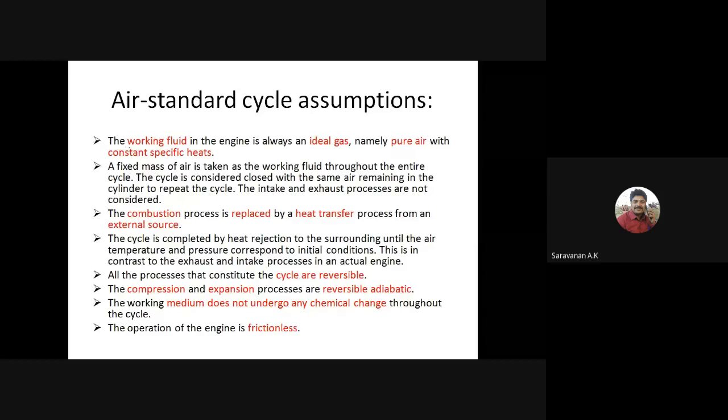So the first term is the working fluid. The working fluid is pure air with constant specific heats. Pure air means an ideal gas, so the ideal gas is used as the working fluid in air standard cycles with constant specific heat, and the mass flow rate is constant. There is a fixed mass flow in the entire cycle.